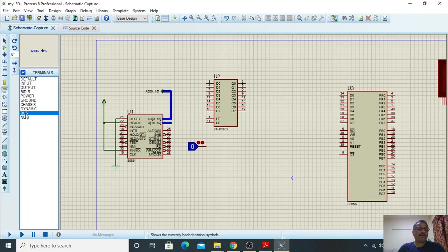If you want to put it once again, click on the bus, place it, keep your cursor here. Now drag it down like this. Try to put a space here because you have to press escape. After clicking only, you have to put escape. Double click.